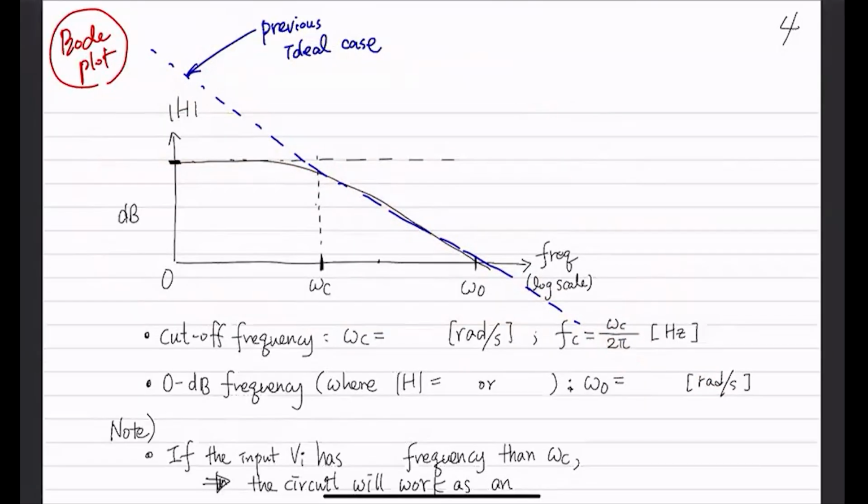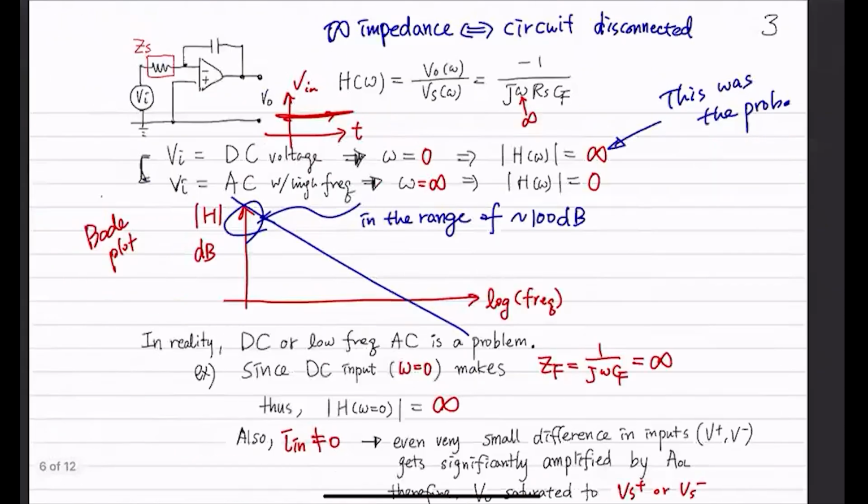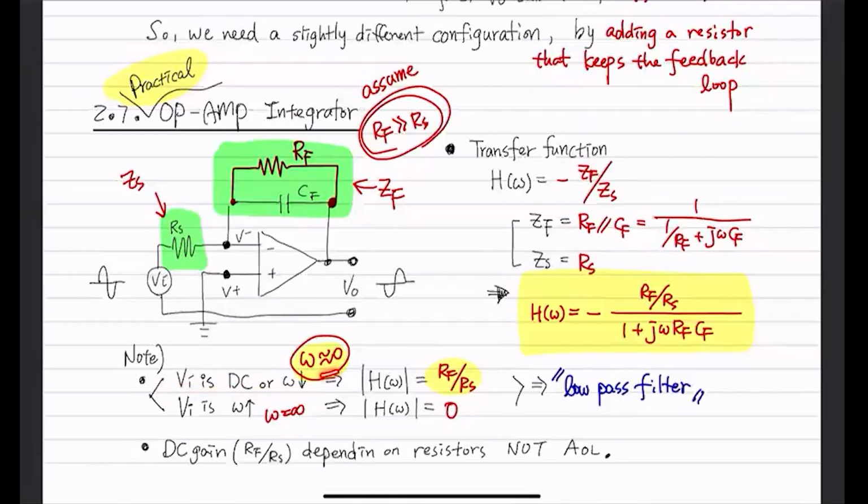If we write this down, the value at this point is going to be, we just found out that here, when we have a frequency that is very low, this amplitude ratio is going to be RF over RS, because you take a look here, the frequency gets to 0, so this whole thing goes away, and just this guy is left, right? RF over RS. And we are taking a look at the magnitude of that, so this negative thing is ignored.